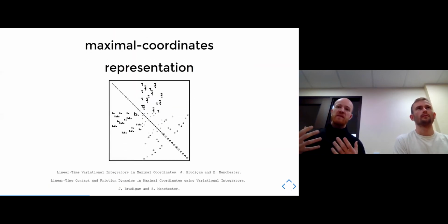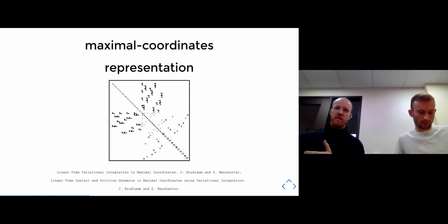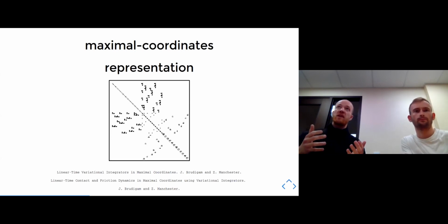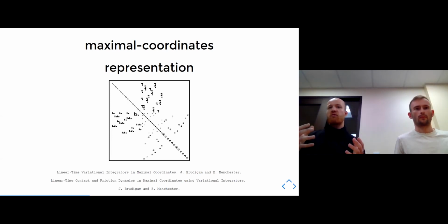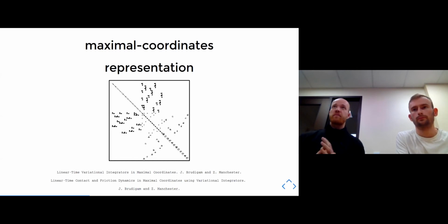And what actually happens is this introduces a bunch of sparsity and structure into the problem. So behind the scenes, when we perform simulation, at the very core is an Ax = b linear system that we need to solve. And this is that A matrix. And you can see the sparsity. It's super sparse. There's a bunch of structure. And we have a custom LDU linear solver that can exploit all of this and really efficiently solve these systems.